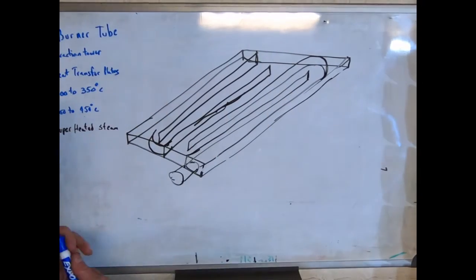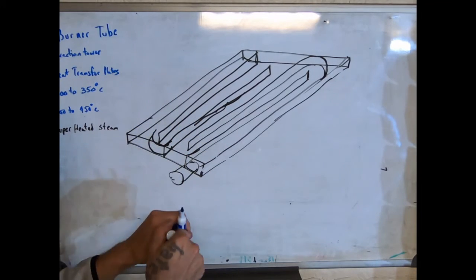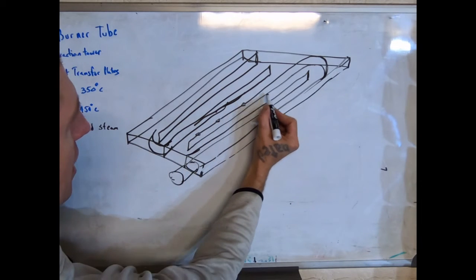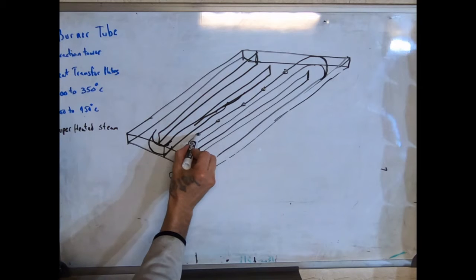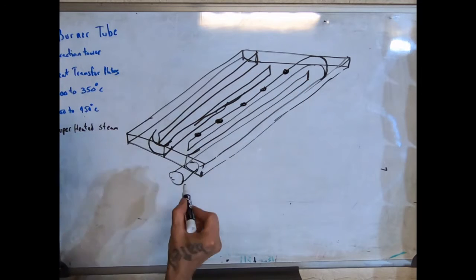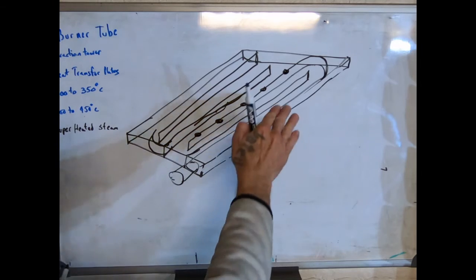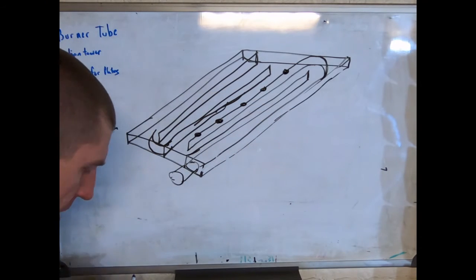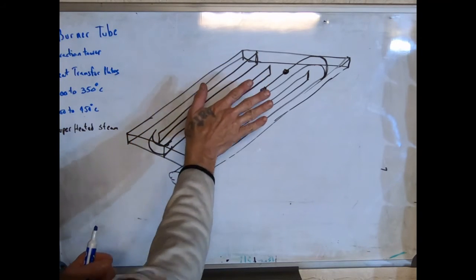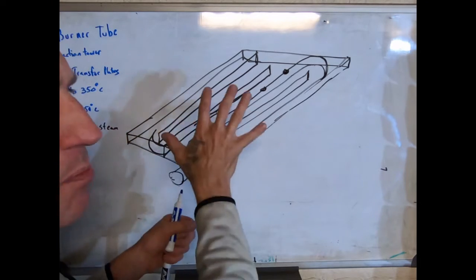And the transfer fluid, and then we would take a flat piece of steel and throw it on the top of it. But that top piece would have holes drilled in it strategically so that we could put a tack bead, a button as I call it, every 8 inches to grab the top of that 1/4-inch piece of metal. Because this transfer fluid's kind of hot, stuff might start warping and buckling on us pretty bad. Maybe not, but better safe than sorry. That'll also keep it to where it can hold pressure, in case even just a few PSIs could bow this thing out a little bit when it's this big.